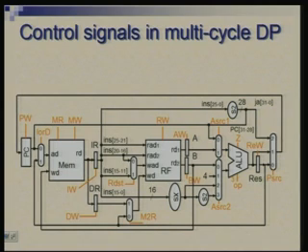Okay. Now, you would notice that there are many more control signals as compared to the single cycle data path we had. So, I will not try to build the table exhaustively for all of these. What we will do is group the related control signals together and also identify the meaningful operations which we will call micro operations. So, for example, PC plus 4 going to PC will be considered a micro operation, right.